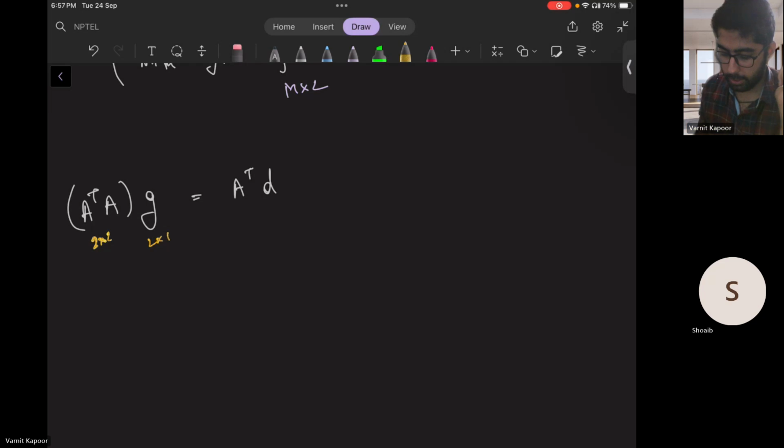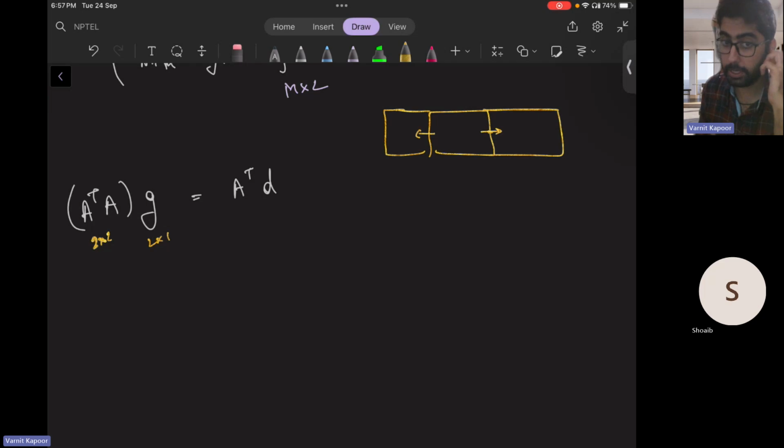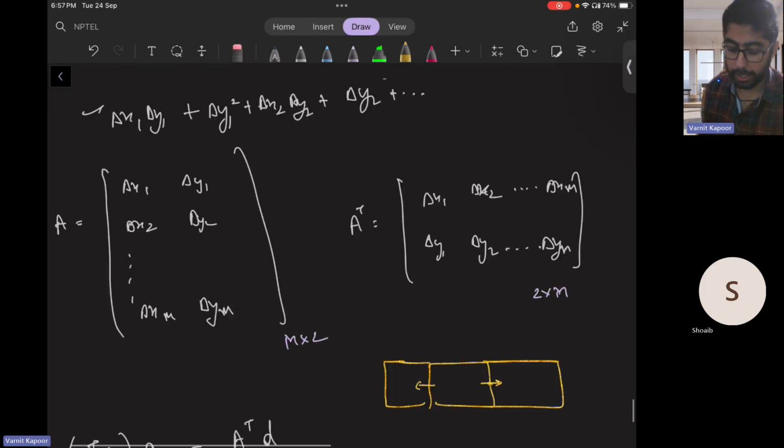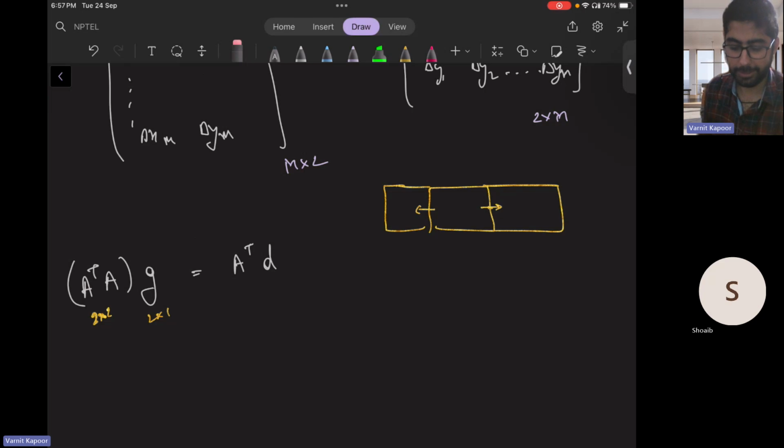The catch is, if you do the dot product for the rectangular structured mesh, here it is pointing in this direction, and here it is pointing in the opposite direction. One coefficient will be positive, one will be negative. Positive, negative, positive, negative. So it won't give a singular coefficient matrix. The way we have drawn the vectors is all different in the unstructured mesh. But in structured mesh, we essentially know, so eventually it will work out. In detail, the professor also discusses this, but to give a brief, it will definitely work for structured mesh. Just one coefficient will be positive, one will be negative.